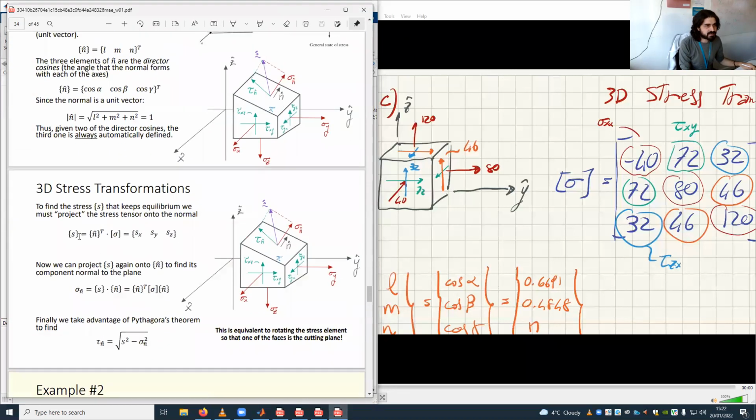Go down. This is S. See, n times t. That's it. And n times sigma gives you S. This S is this vector here that was neither the normal stress nor the shear stress, it was the composition of the two stresses. Since we want to find sigma n already, let's use this one straight off the bat in MATLAB.